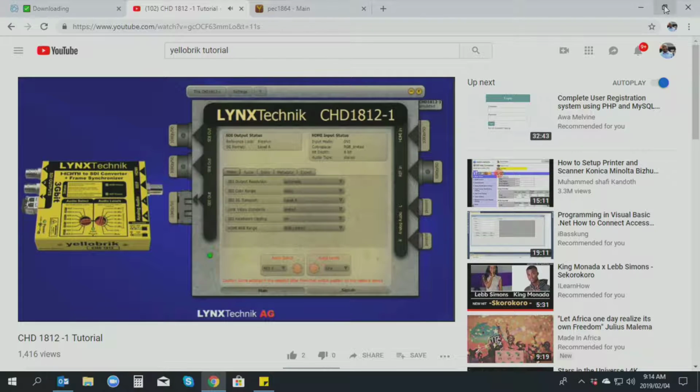You think the module's broken because you can't see a signal, when actually the signal's there, you just can't process it because you're not 3 gig compatible. And this happens a lot, certainly with people connecting up to a lot of consumer devices, because pretty much everything does 1080p 60 now, and we're always outputting 3G, and it always causes people problems because they want a 270 megabit or they want a 1.5 gig because they're a 720p plant.